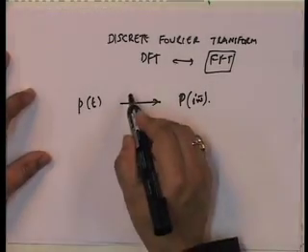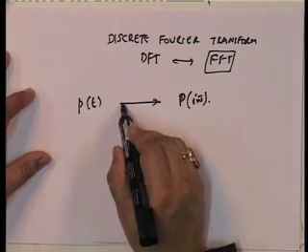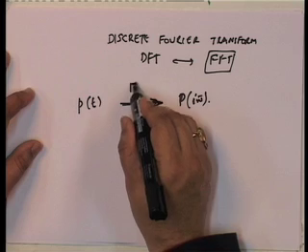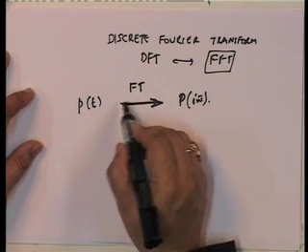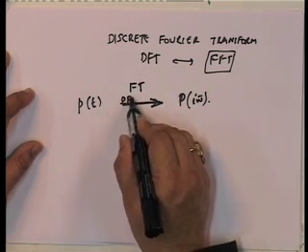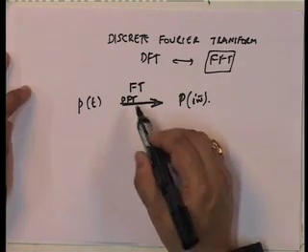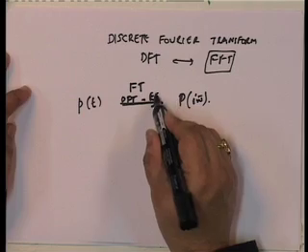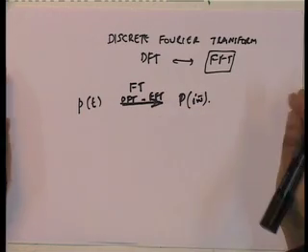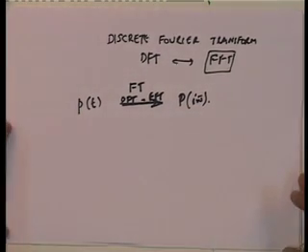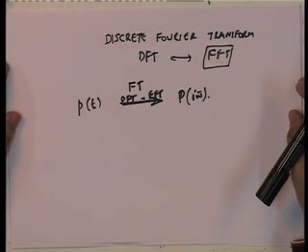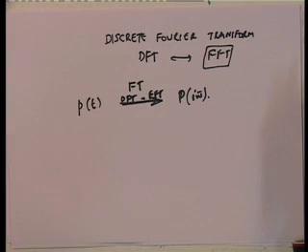So, essentially this procedure going from here to here is the Fourier transform, and so we use the discrete Fourier transform. I will write down the discrete Fourier transform, and the FFT, which was developed by Cooley-Tukey at the IBM lab, was essentially a faster way of doing this DFT.